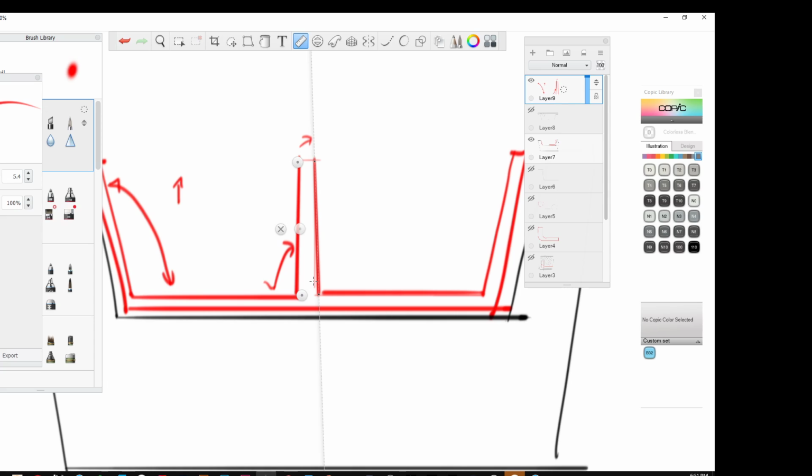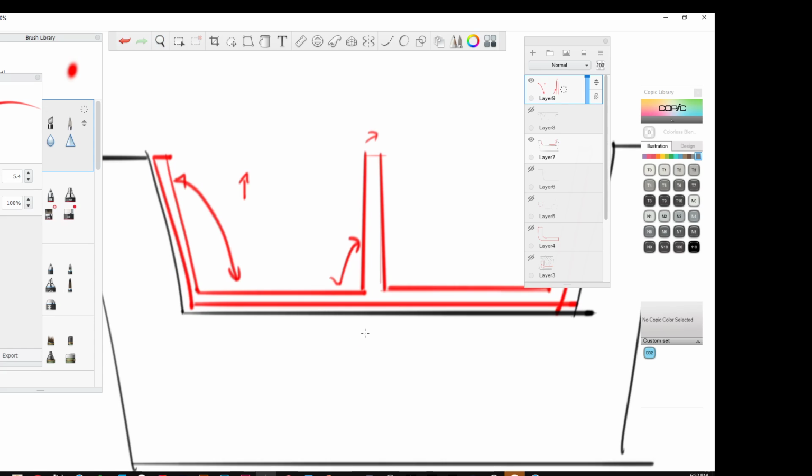And for the most part, you guys don't need to worry about these unless you really want to show the part. For example, I may do a 3D prototype for someone, but it's only going to be a prototype. So if I'm 3D printing it, I may put the ribs in there for structural strength, but I don't worry about putting draft on my ribs. I'll put the draft on the outside if that's noticeable, but I don't do drafts on the rib because I'm not pulling a tool off of it. But what that means now is this rib is the opposite direction of there, so that you can pull your tooling off. And again, that needs to be the minimum draft. You can get away with less draft if your rib is only so high.